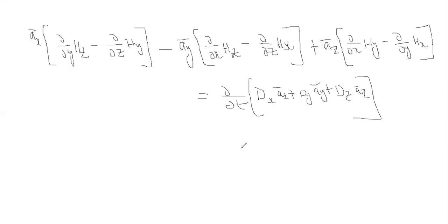Varying means ∂/∂y is varying with respect to y, and ∂/∂x with respect to x. They are not varying with respect to y and x, and can vary with respect to z only, meaning only ∂/∂z can be nonzero. So wherever ∂/∂y and ∂/∂x are there, that value is 0, and we have only ∂/∂z because the electric field and the magnetic field vary with respect to z.